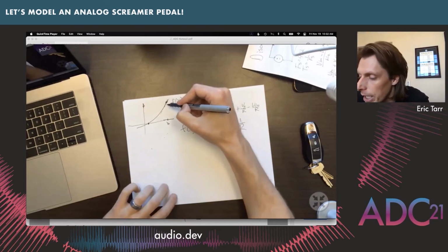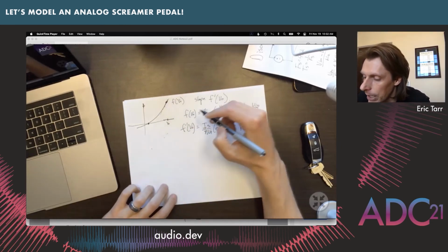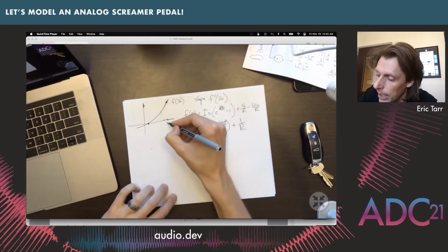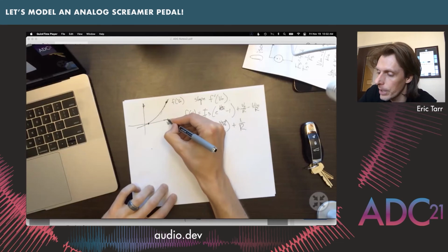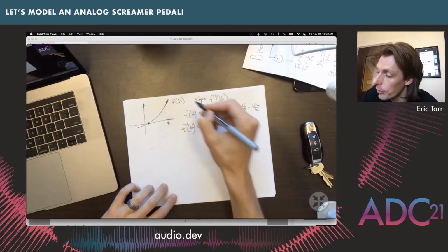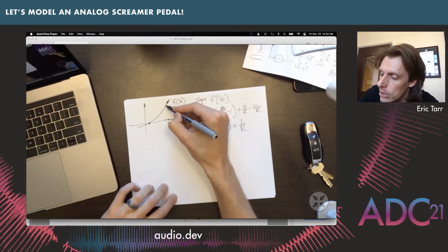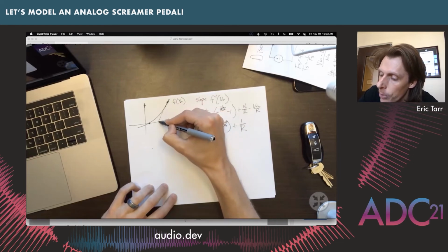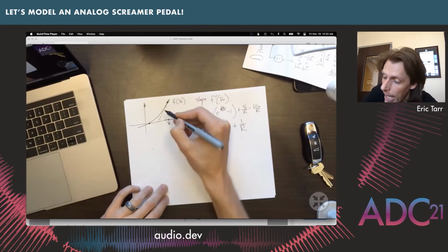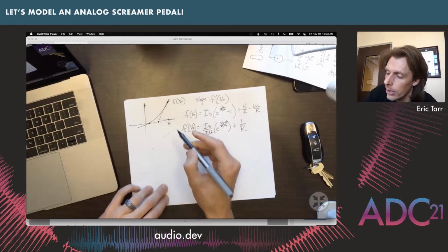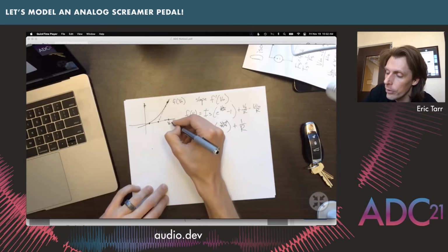So what we're going to do in an iterative process is take what we know at any given point in time, which is our V out value. We plug it in, we get a value for the function over here, and then we get a value for the slope. And we can use those things to help us find a new point where we're going to jump way ahead to something that's hopefully closer. This is V out for our first guess, so guess 1.